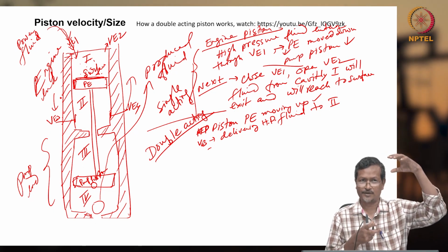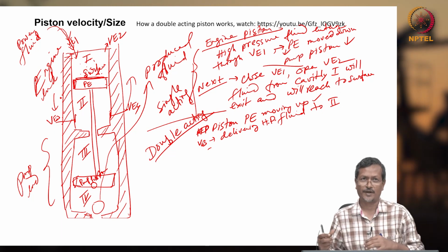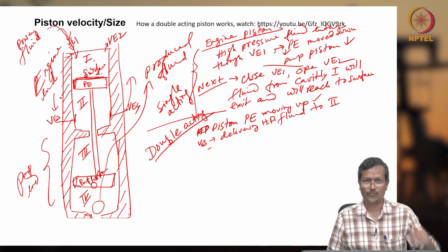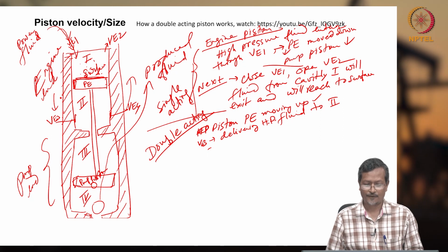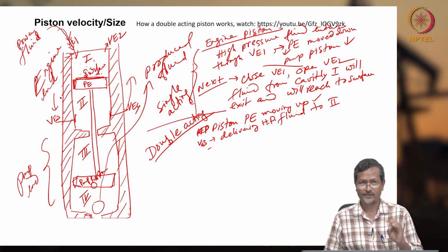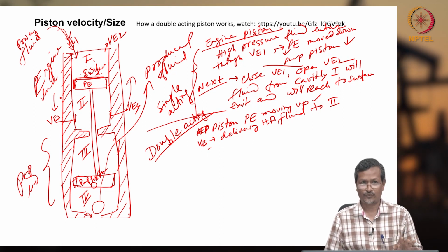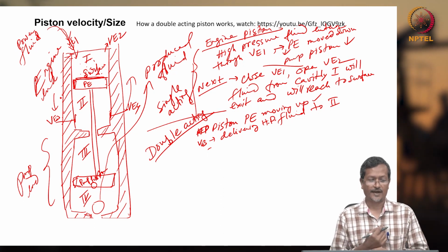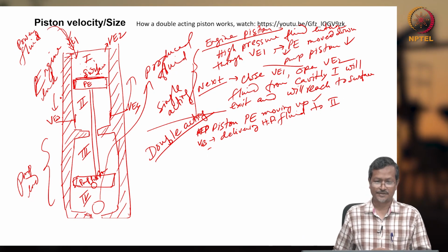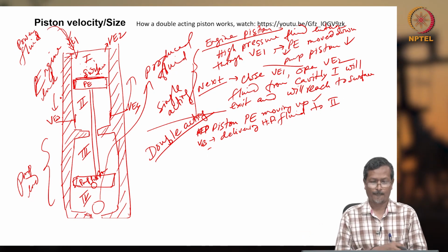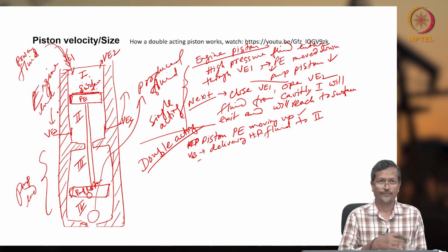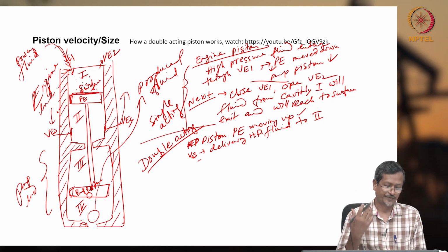And because this is a short pump, short means less than a sucker rod pump or beam pump, you can go to very long depth because you don't have a very long sucker rod, which would create surface motion and other issues. Again, it is a low flow rate pump, gas will be a problem, sand will be a problem. Normally it will not be used for gas well deliquification because high gas volume will create issues. And very high piston speed also creates much trouble. Major failure occurs because of excessive piston speed. So if very high speed is there, you have to control your pressure from the surface and reduce the speed.